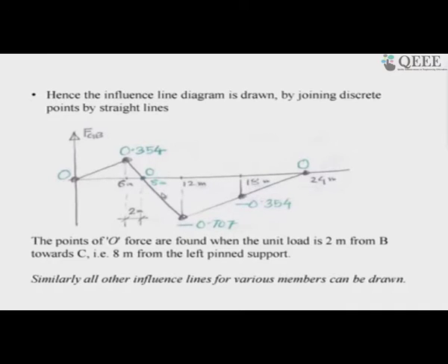So, in between, if the unit load is onto the floor here, I have the effect here, and I can interpolate and determine. This looks very easy, since these are straight lines to determine in between effects. We will see it is not that easy for statically indeterminate structures. For the determinate structures, it is.